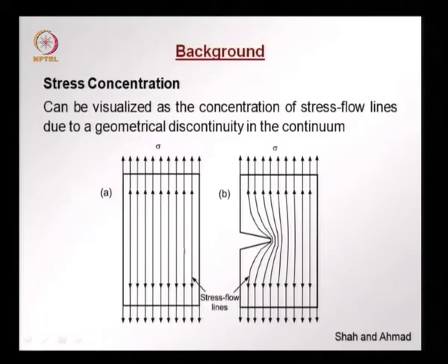Now, going back to the channel with water flowing example, think of what will happen if you put your hand at one of the edges. You put your hand into the flowing water, and what would happen? You would have water moving faster along the edge of your hand, because you have blocked a part of the flow, and you will find some eddy currents forming around the edges. So, there is a concentration of flow, a faster flow occurring at the edge of your hand, because you have blocked part of the channel.